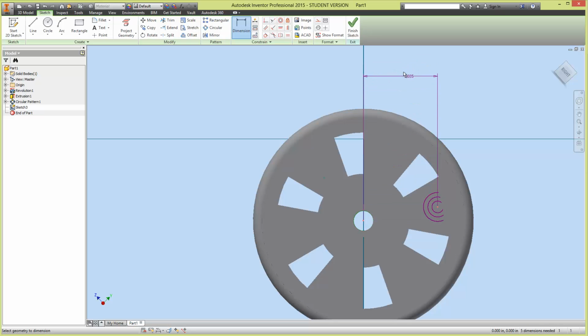So in order to fix that, if you right-click and then go to the option called Aligned, you're going to get an aligned reading because it's going to twist the dimension a little so that you're getting a more parallel or collinear view of it. I'm going to click over there. I'm going to set that to, let's say, 0.7, which it said on the sheet.